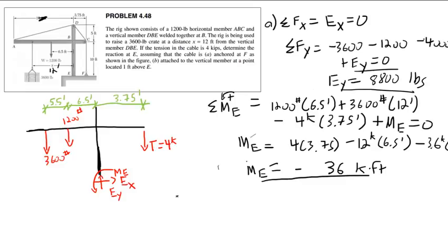All right, so let's keep going. Now let's do part B. With part B, we are now extending this force. Instead of this force attaching to the ground here, it is now simply being attached to the vertical member. Now this no longer is an external force, so it's not going to affect the reactions at all. One force vector comes up from this point, another comes down from this point, and they cancel each other out. So the free body diagram for part B is a little bit simpler. It's just the same free body diagram, but without this force here.